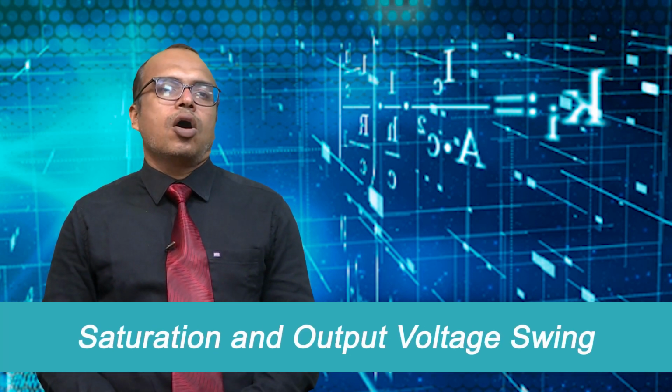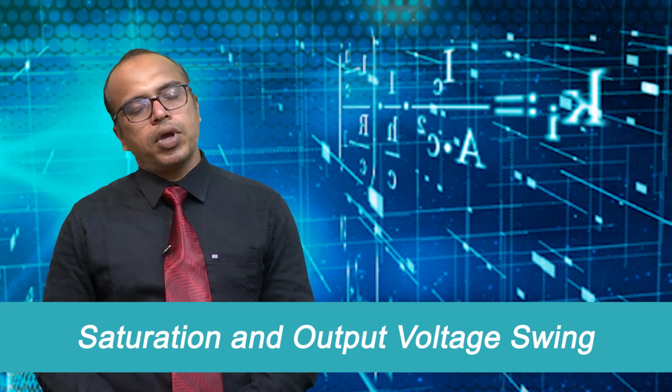The next point is saturation and output voltage swing. Operational amplifiers have finite output voltage swing capabilities. If the multiplied output exceeds this range, the op-amp saturates, leading to a distorted output signal.